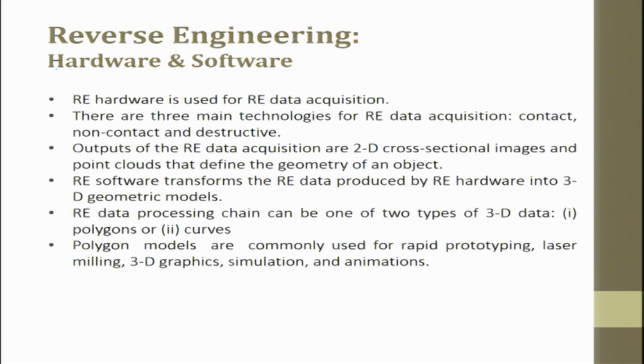Talking about hardware and software, which is very important. If a hardware captures a signal with noise, then the software can be used for removing the noise. But if the hardware could not even acquire some data, software always works on the hardware generated data. You can have a higher end software which can work to the finest accuracy, but if the acquired data itself is not of the highest resolution, the software cannot improve the resolution of the product or of the reverse engineering point cloud data.